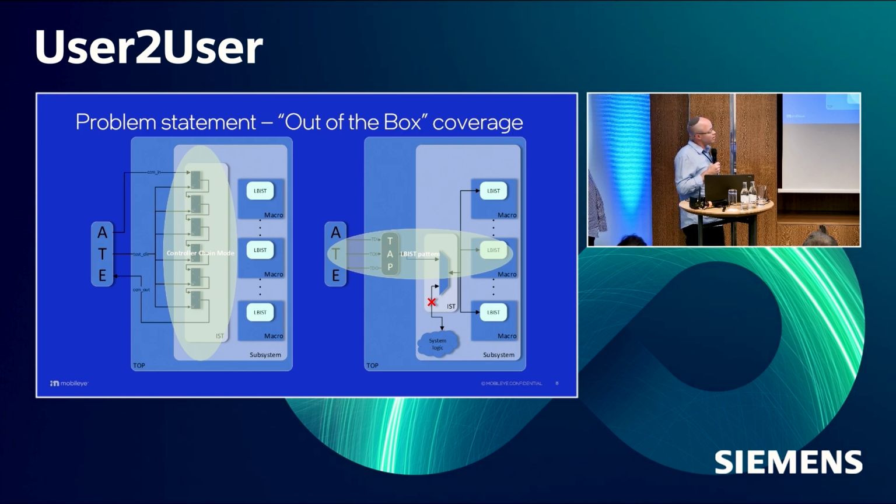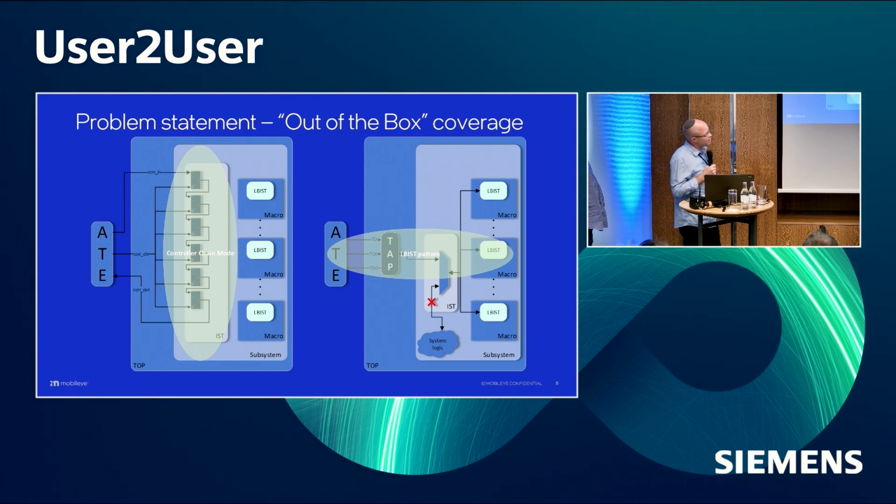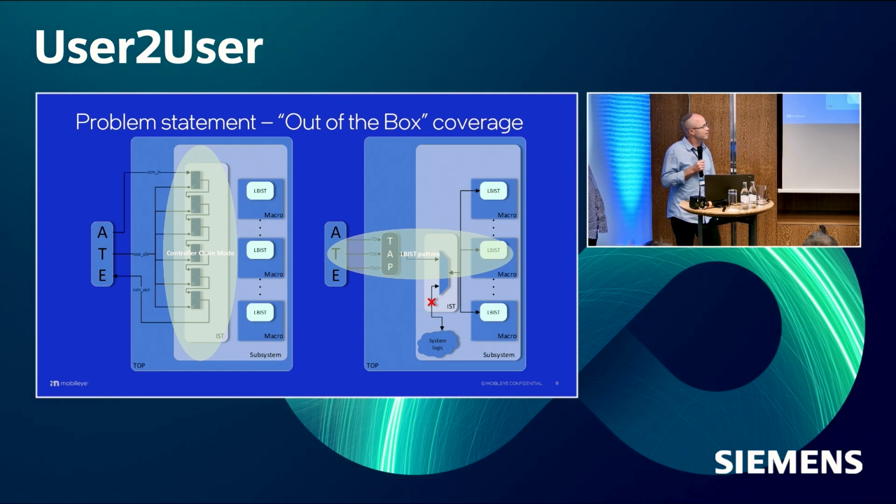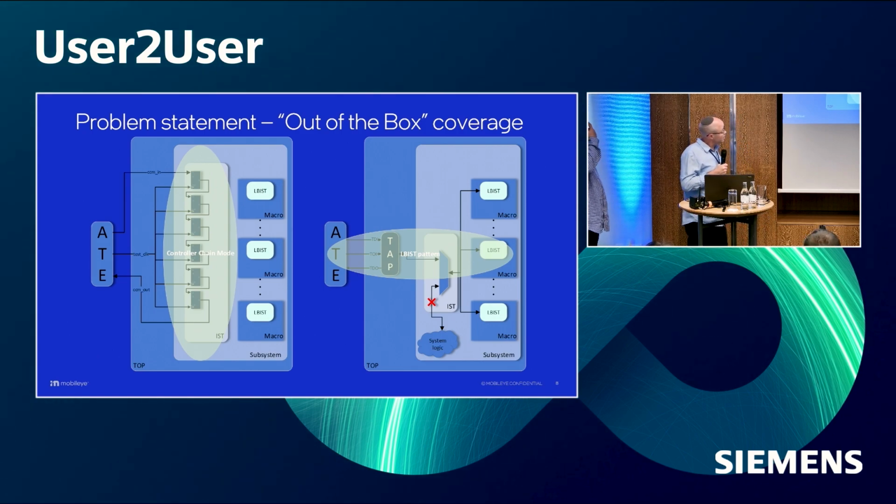And then we have another option to use a JTAG-based directed pattern. They're aiming at the BIST component directly, again using the test interface, using the JTAG interface, TCK and test interface. So again, both these options come out of the box from Tessent, but as you can already see, both use a dedicated test interface. Now, how does it look in real life?